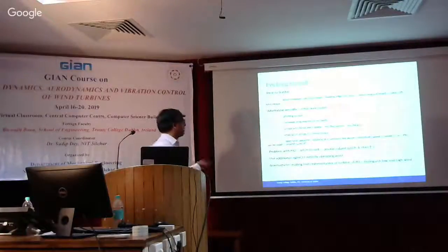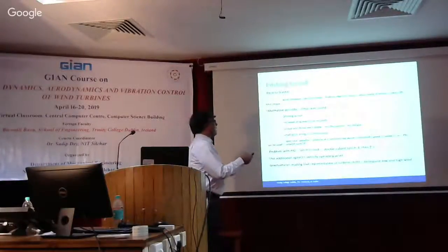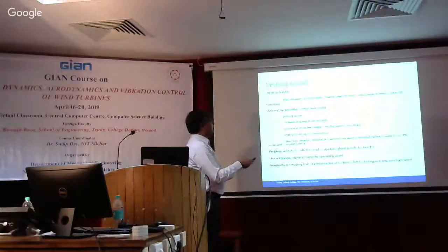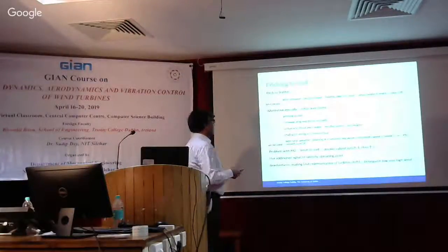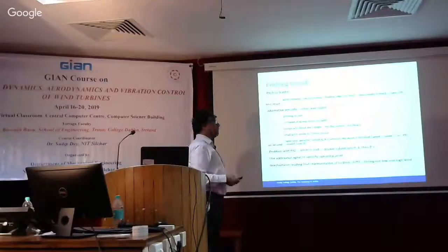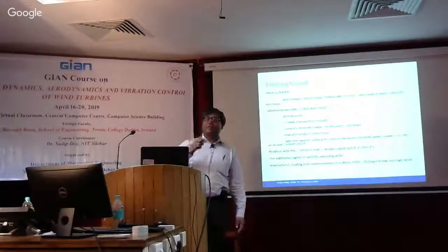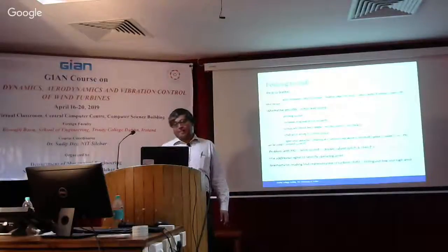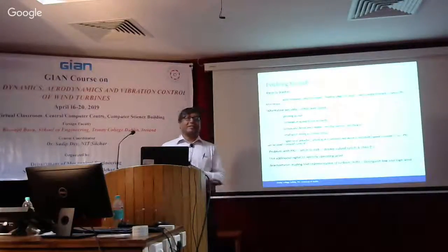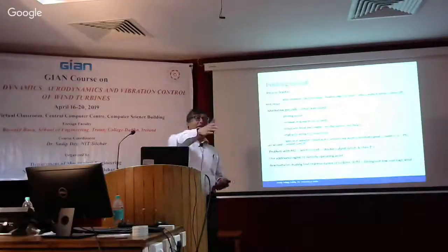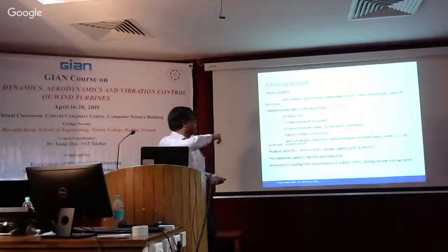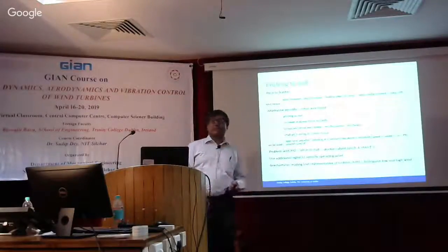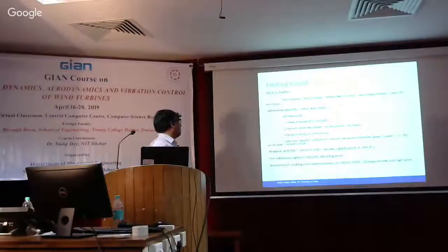So you can use pitch to feather the wind, and basically they place the leading edge to the wind and reduce the current to limit the torque. And essentially, this is done when wind turbines are taken out of operation. So a lot of the times, if you notice when you're passing by a lot of wind turbines, you see that it's not rotating, but the blades are somehow kind of feathered out. Actually, in a location, they're just static at a particular position, which is basically feathering out. The pitch control is used to do that, and that stalls the machine.